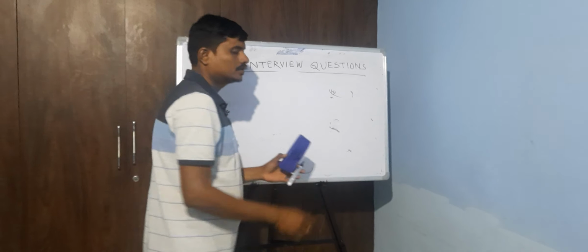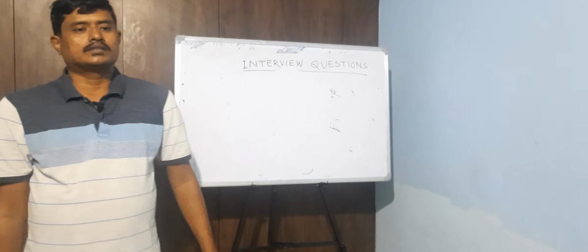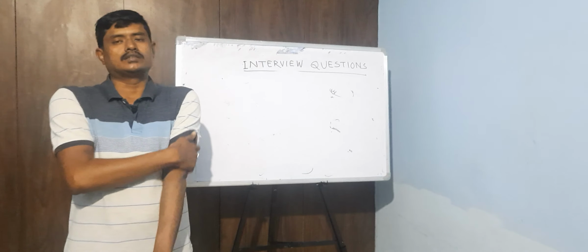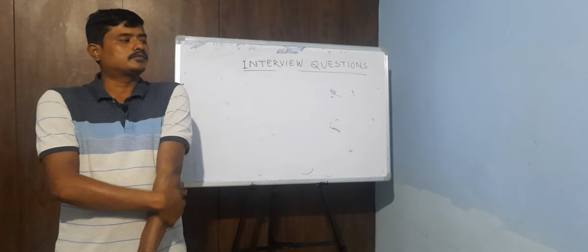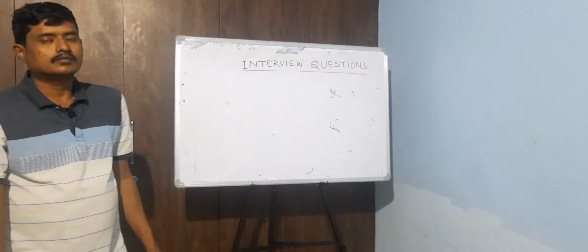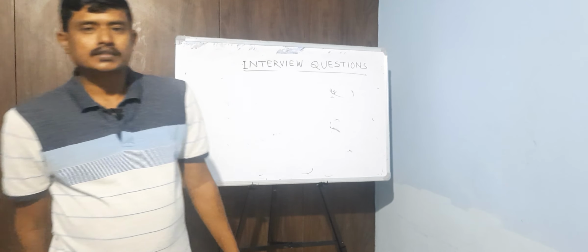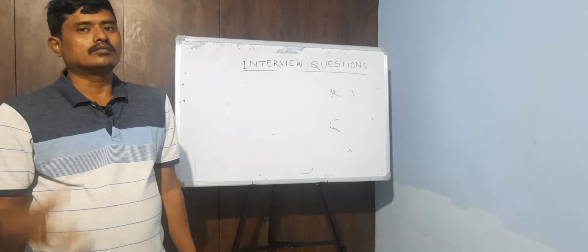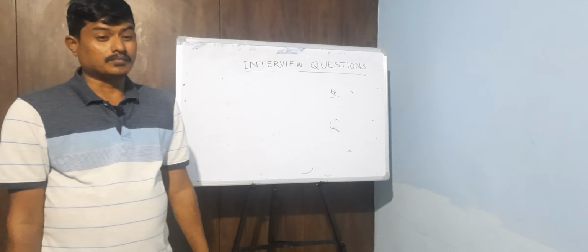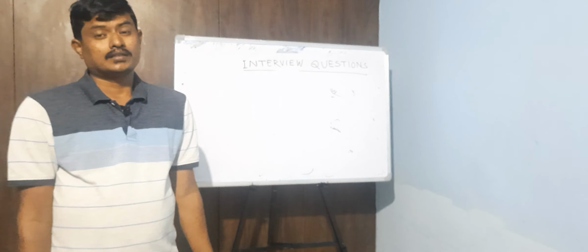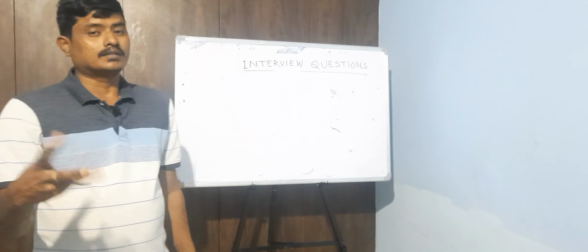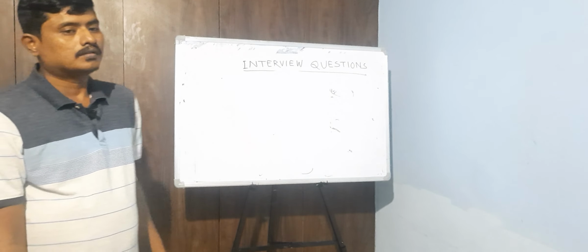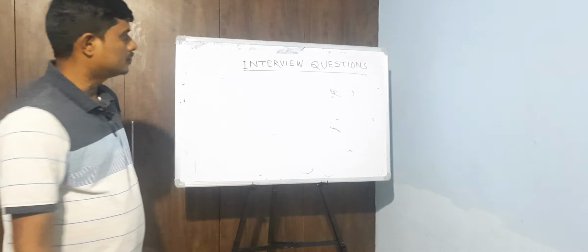Then come to the Buchholz relay. From the name we know it is a relay. It is a gas actuated relay. What is the function of the Buchholz relay? Its function is to protect the transformer from any internal fault, any insulation damage of the winding, any gas formation in the transformer, or a decrease in oil level.